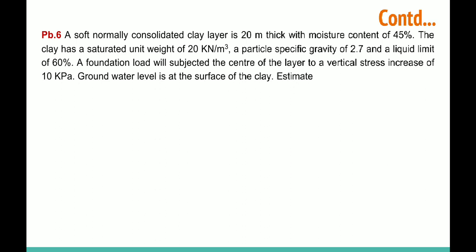A foundation load will be applied at the center of the layer, giving a vertical stress increase of 10 kilopascal. Groundwater level is at the surface of the clay. Okay, so all this data we have: specific gravity of solids, liquid limit, and saturated unit weight.